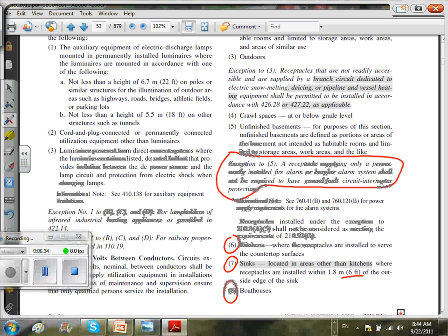Regarding the clause about readily accessible, it's one of the questions in the homework. Say you put in a freezer. Typically, you put an outlet with the freezer. In 2000, the outlet, it's no longer accessible. In 2011, they start requiring all these locations of GFCI to be readily accessible. Before that, not a big deal. Readily accessible means you can't climb or push or pull something.